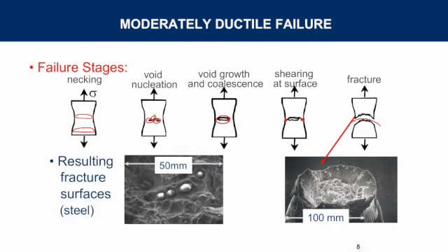Okay. This is an SEM of the voids. So when you take a SEM, scanning electron microscope, you plate the material in a gold film, and when you do that, these air pockets actually get kind of filled in with the gold material, so they look like metal beads, but they're actually air pockets. So these are those void nucleations that are occurring.